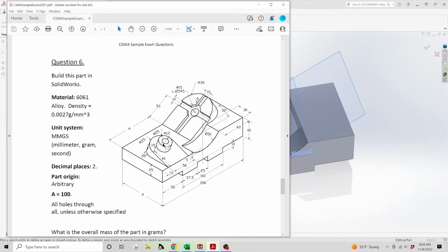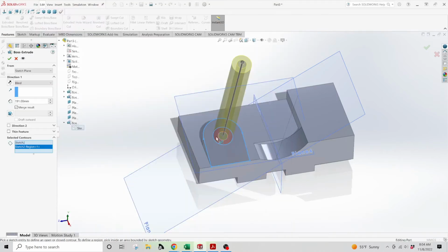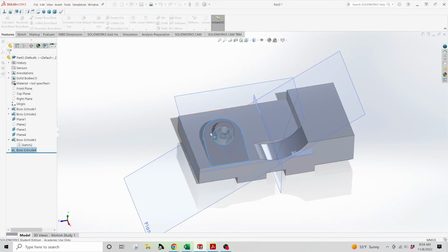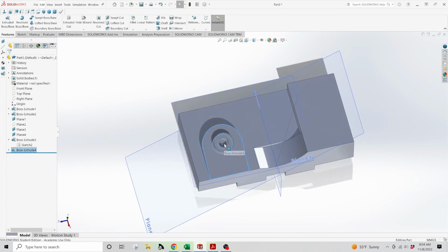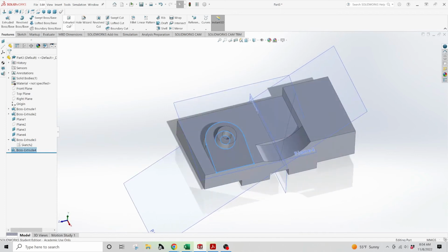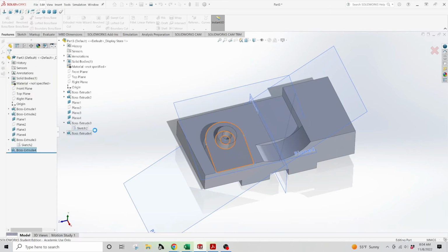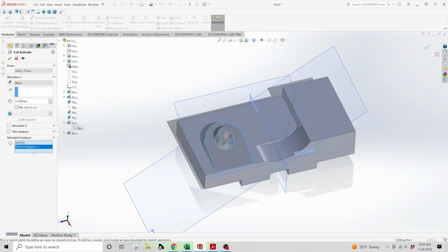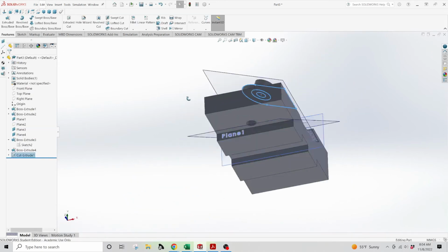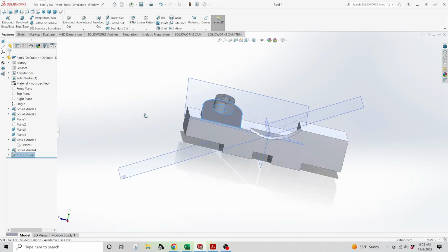This is probably a through-all hole, it looks like. Yeah, so I'm going to make that a through-all hole. I'll do one last step there, but this is 15 millimeters. Okay, 15 millimeters. This needs to be a through-all hole, so I'll do a quick extrude cut, again referencing that same sketch. It'll be this. Through-all. All right, so now we have that feature created.